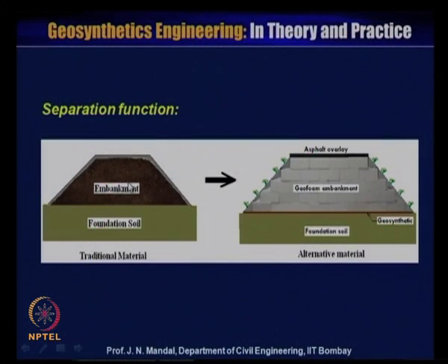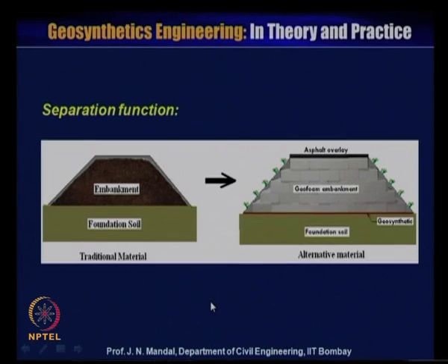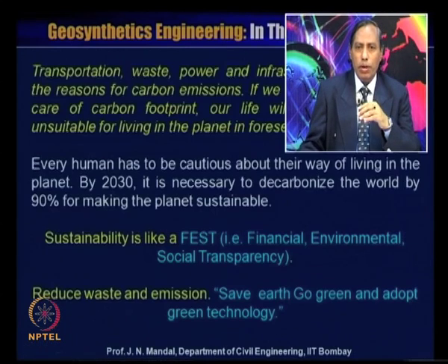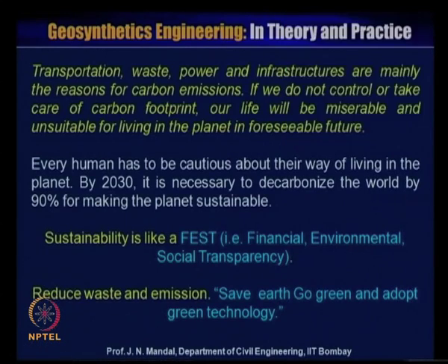So, this is the application of the barrier function in the case of landfill, dam, canal and reservoir. Also for the separation function, instead of the conventional material, one can adopt geofoam material, which is very light, and also he can save a lot of carbon dioxide.